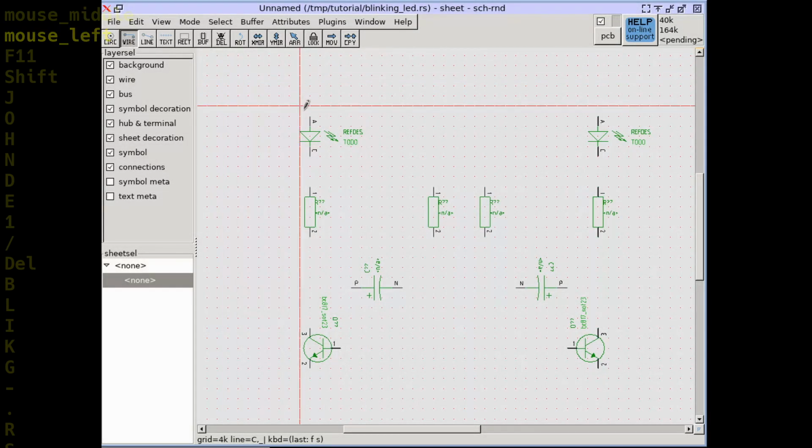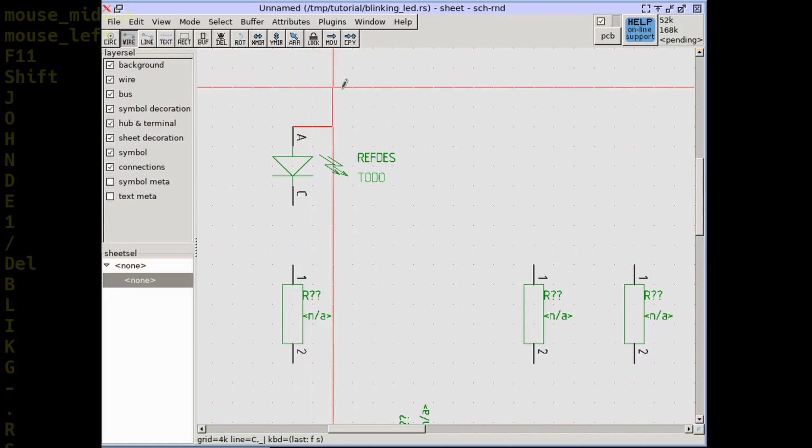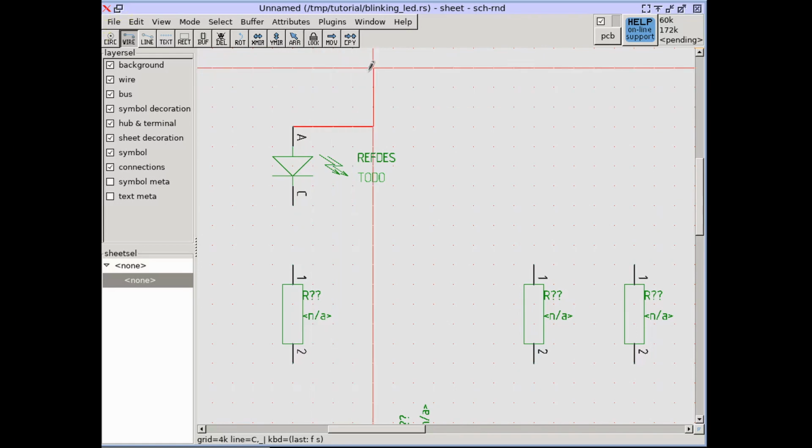Clicking the wire icon in the toolbar activates the wire tool. Click at the starting point of the wire. The crosshair starts to drag a dogleg of 2 thick red lines. This indicates the 2 wires that would be drawn on the second click.